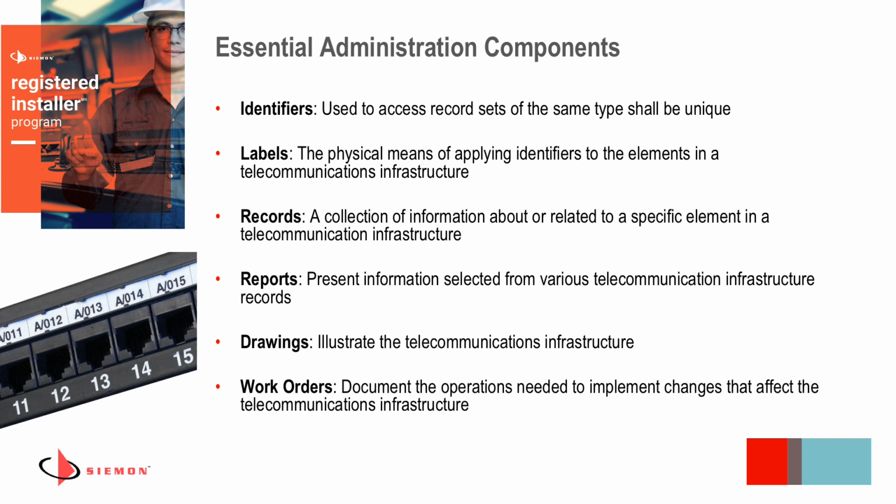The record keeping, the ability to understand and document which of those cables goes where using those unique identifiers, as well as the ability to provide reports as needed, usually through a database type of system. Drawings of the telecommunications infrastructure, the blueprints, if you will, dating myself a little bit, but the blueprints of your cabling system, identifying where the drops are, where the telecommunications rooms are, and all the details of your telecommunications infrastructure, as well as work orders that may have affected anything that has changed since the original documents have been provided.